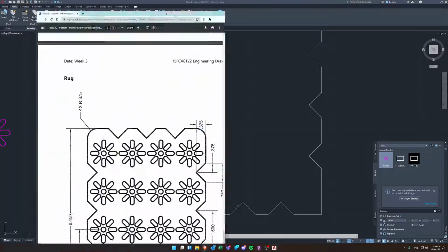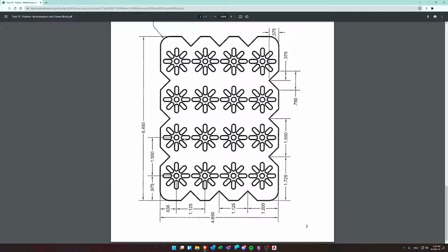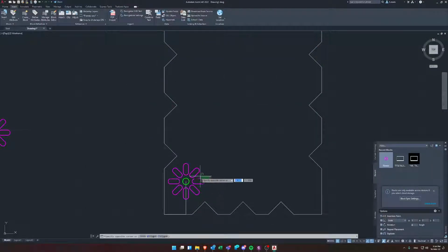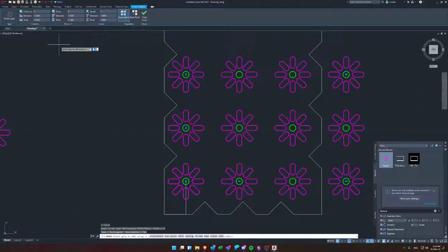Okay, let's look at the drawing now. Now I have a lot of them, and if I have a pattern, then I can use array for that. It's going to make my life much easier. I can see that I have 4 columns and 4 rows. So let me close this and choose array, rectangle. The columns are 4 and the rows are 4 as well.